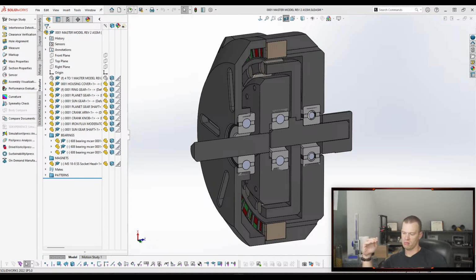So that's one workflow that we've used in the past that's successful, because we have revision control on the folder part that has all the sketches, and then you're modeling your geometry to those sketches, and if that changes, we have revision control on that, and it'll also update your part file with the changes based on that folder part. Now the question is whether or not you would have the similar functionality with this master model technique.